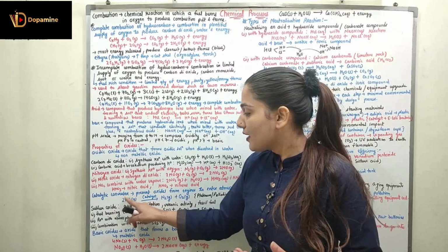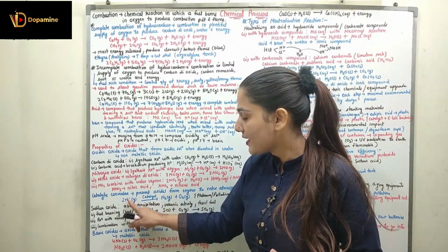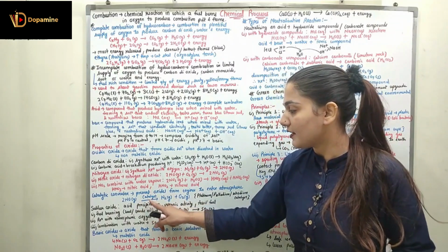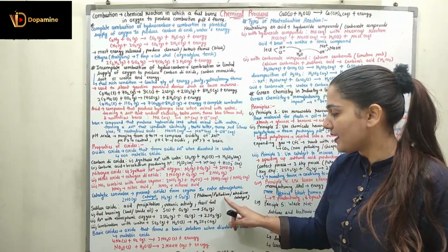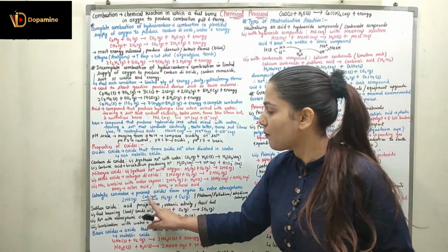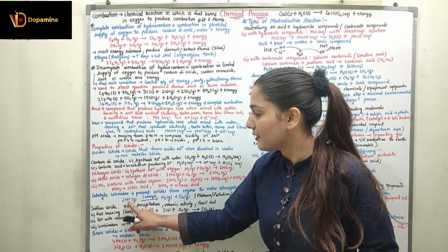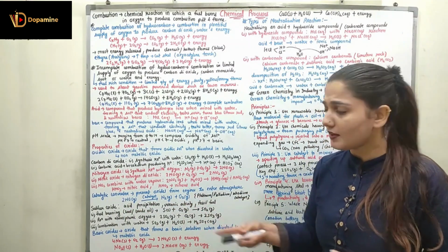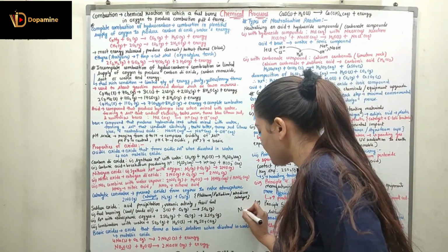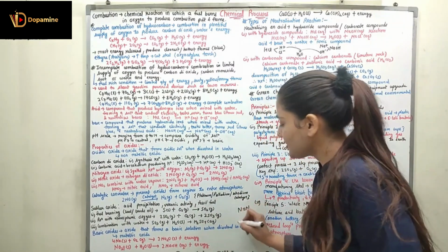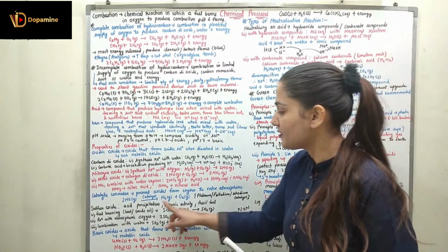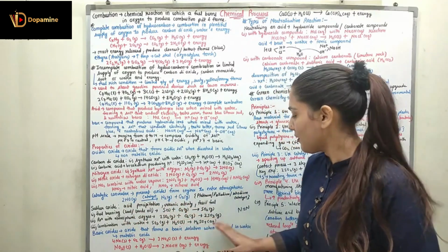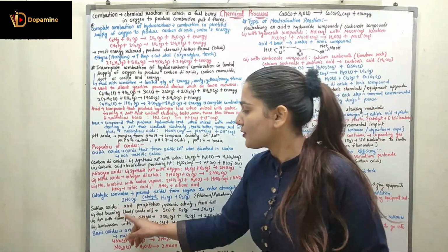It is going to take this nitric oxide, and the nitric oxide, with the help of a catalyst present in the catalytic converter, the catalyst over here being platinum, palladium and rhodium, is converted back to nitrogen and oxygen. Now nitrogen N2 is connected with a triple bond, and this is stable. So when this N2 gas is formed, it is stable and the reverse reaction would be very slow, right?